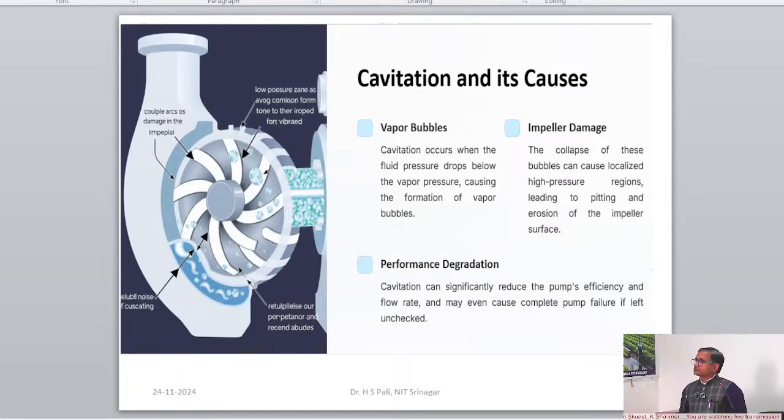On the main vertical y-axis we have the head pressure, and on the horizontal x-axis we have the flow rate. Basically, as far as the pump is concerned, there are only two parameters, and if you want the performance or efficiency, or the installation, then these two important parameters we have to look after. First is the head. Head means pressure, simply in simple language, the pressure. Another is the flow rate or discharge.